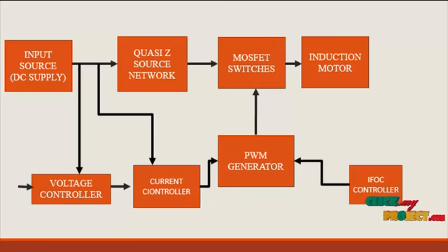Voltage drop can interrupt an ASD system and shut down circuits, loads and processes, and the performance and reliability are compromised by the VSI structure. Also the dead time and common mode voltage problems increase in the conversion method, which are eliminated by using the indirect field oriented control method. So the recently developed Z source inverter has rectified that kind of problem.